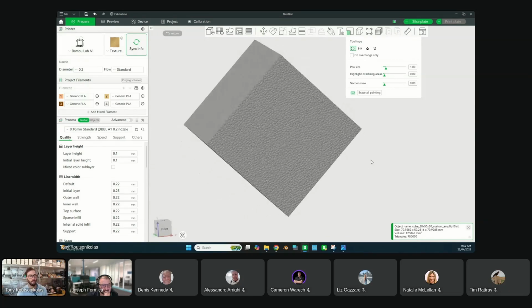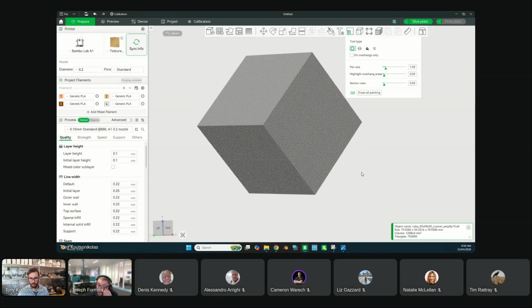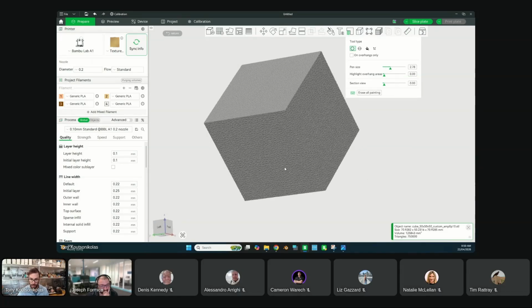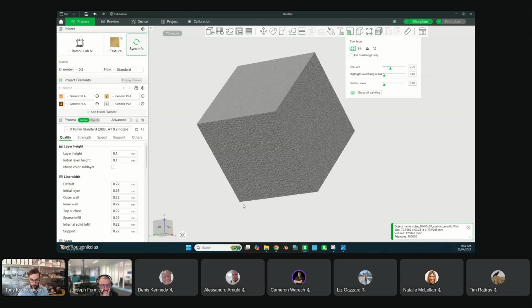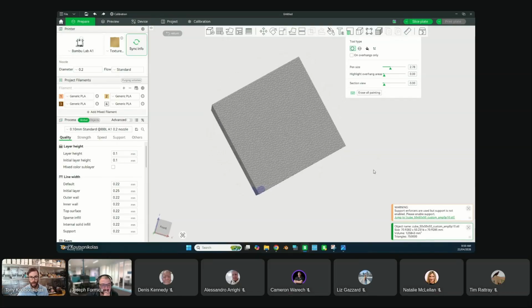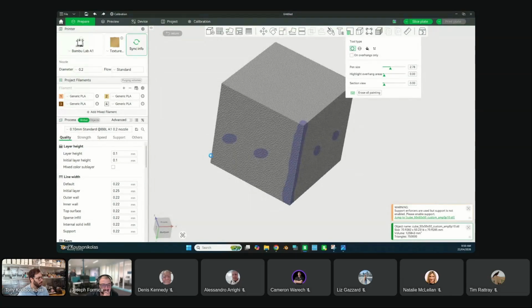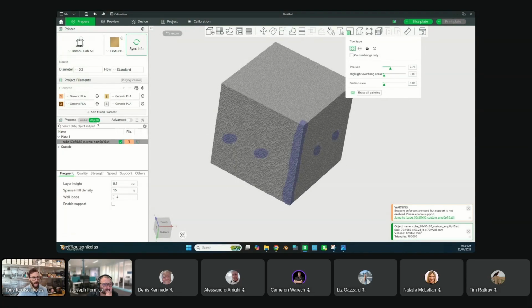But I actually printed basically max height on one of our printers, so it filled up the print bed. I printed a part like this. It basically had zero contact with the print bed, but I just used support material. What I do is I increase the pen size on the main edge. I think that's what I did. It's this initial one, because I wanted a good base. And then every so often, I did a dot like this on each side. So I'm painting on support there. This car part needed support right near the top as well, so it also had another connector right at the top, like a big solid tree, which was good.